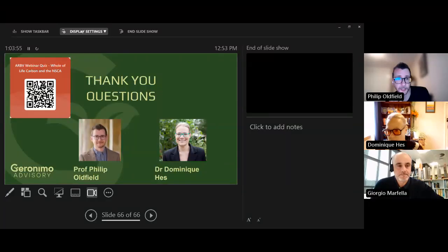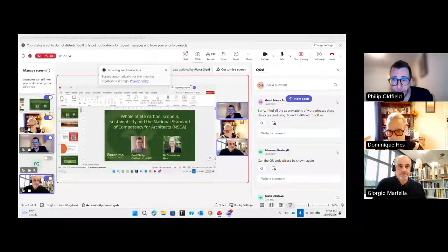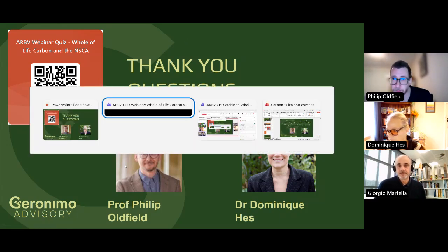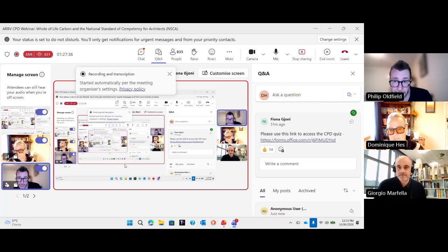Yes, so I can partially answer that. There's a huge amount of different software out there. I use Microsoft Excel because I like to see the numbers go in, and you can just multiply it through Excel. It depends how you design as well. If you design in Revit and in BIM, there are lots of plugins for Revit, things like Tally. We teach the students at UNSW Tally. We teach them by hand in the first year, so they do it via Excel in the first year. And in the second year we teach them Tally because they all use Revit. If they build a Revit model, Tally will pull the data straight from the Revit model. So if you're designing in Revit, something like Tally, there are other ones as well.